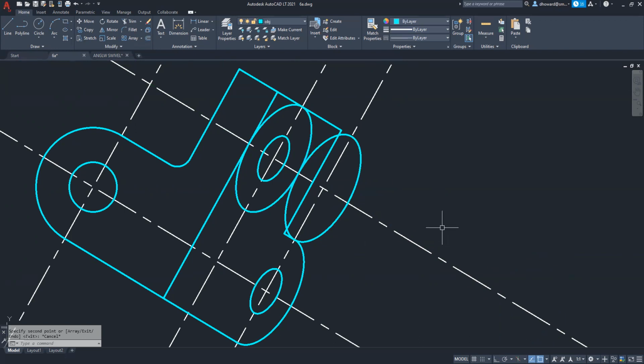The way they made it super easy for us by everything being so balanced with these 3/4 inch offsets. So these sides all line up like that. So I'll do that one more time. Before I trim this guy away, I'm going to copy him. C-O, enter. And just grab him from this point here and copy him to there.